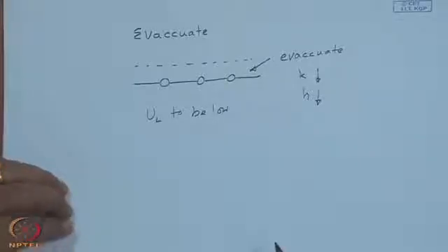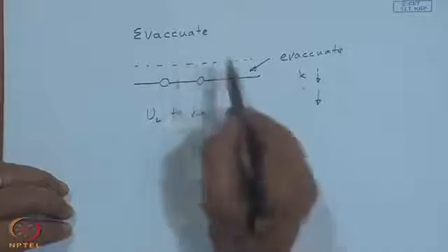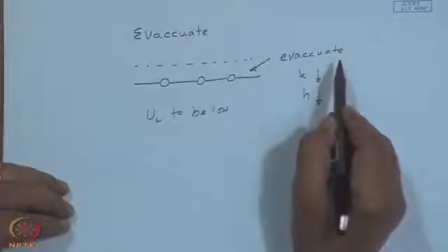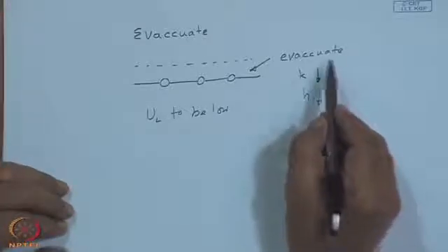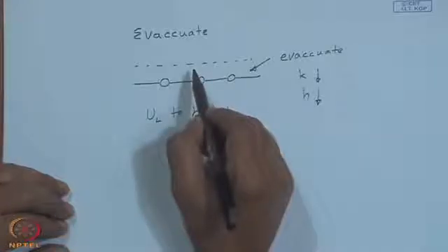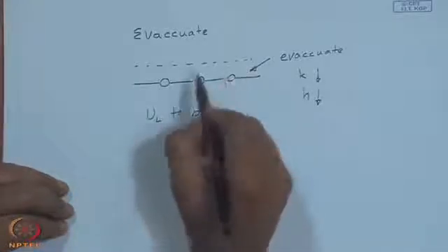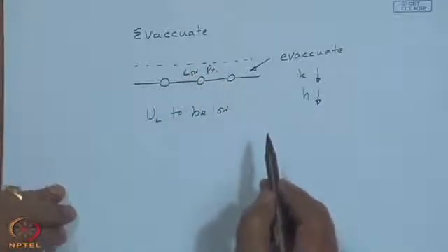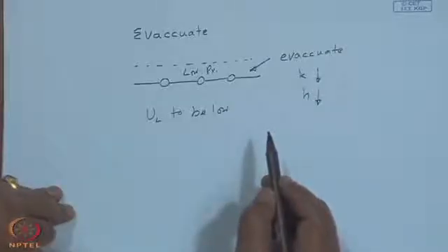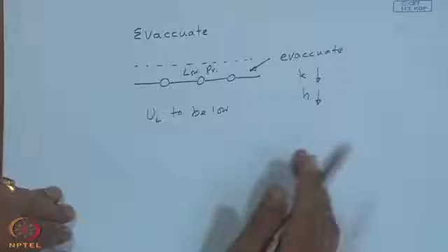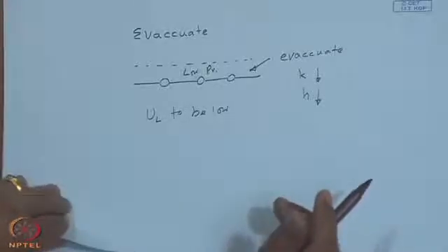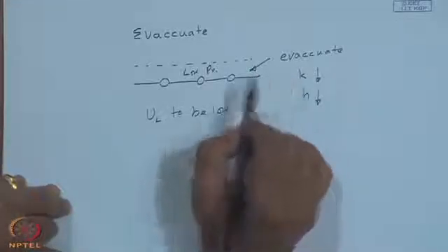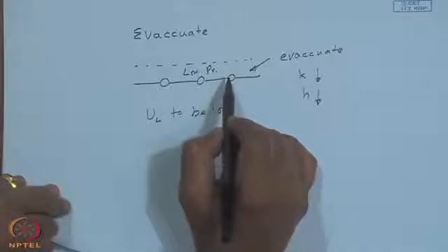The problem will be, this is a large volume for a flat plate collector. So, maintaining a low pressure through evacuation and sealing can be a problem. Then if it collapses for some reason, the glass is likely to break because of the low pressure region over here, and if there is a leakage, there will be a loss of vacuum. Consequently, again your overall loss coefficient will increase. So, it is not practicable to maintain a completely sealed evacuated flat plate collector, though there have been attempts.